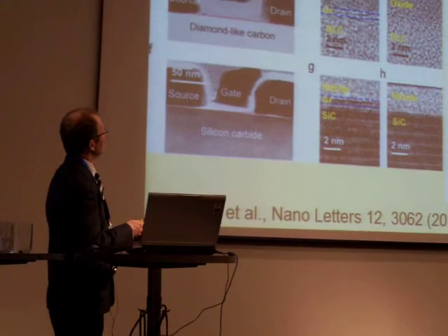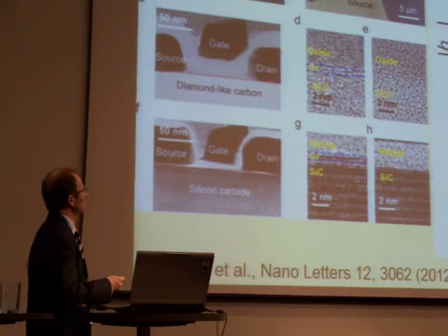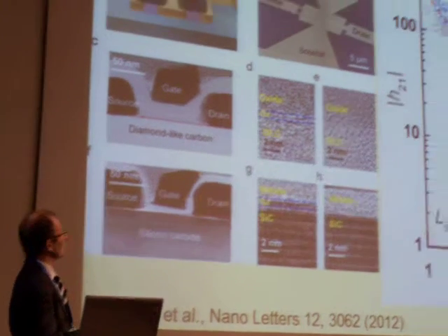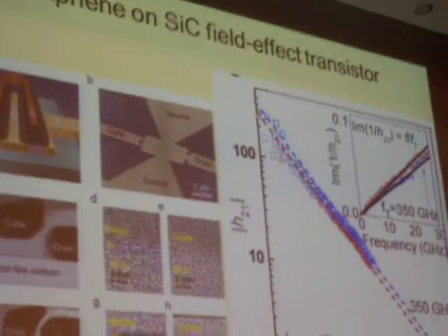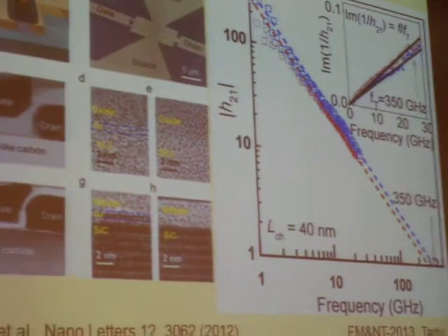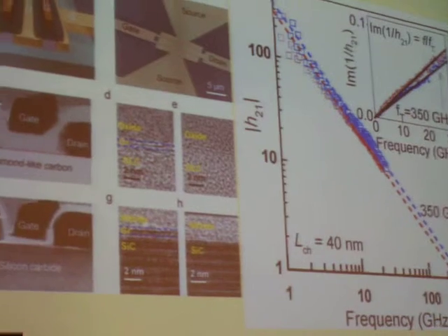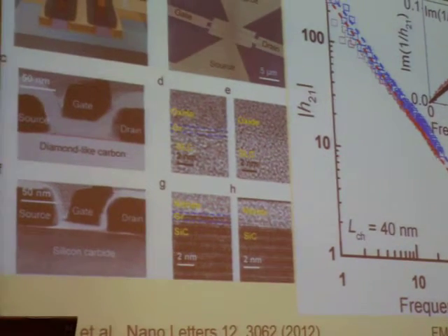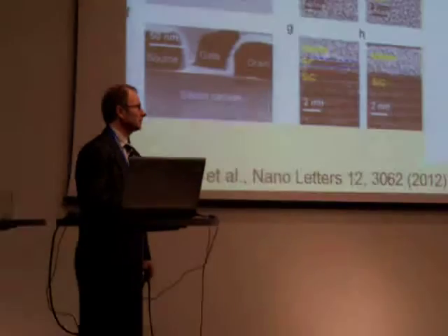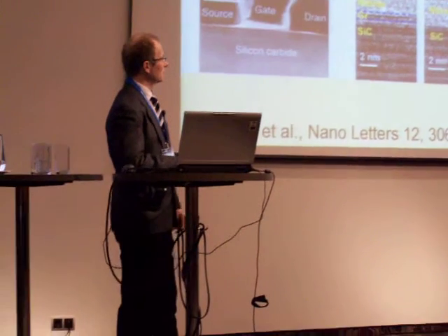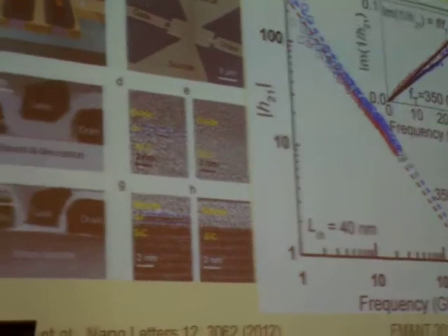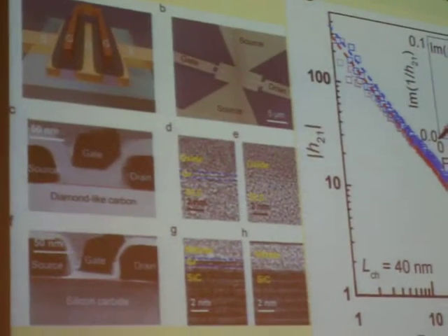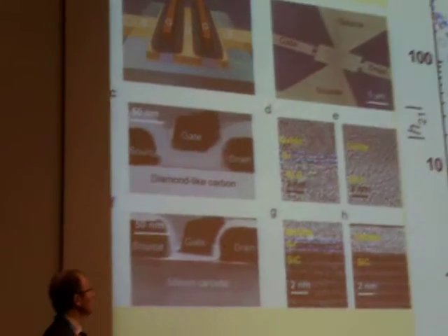It has been reported lately by IBM group that the record current gain cutoff frequency exceeds 300 GHz and is comparable to that of the fastest nitride-based field effect transistors. It's worth noting that cutoff frequency is related with average drift velocity and energy relaxation time in graphene channel.